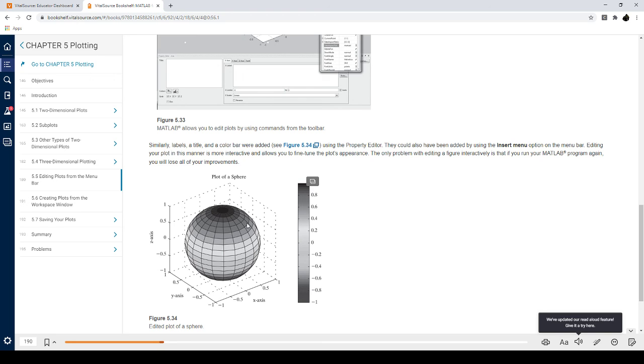And this is something that you'll see a lot of in FEA. Whenever you start doing simulations of designs, there's usually a color scale attached to it that tells you where the sharpest stresses are, where the most stress is being located, and it helps you locate it faster using the color wheel. So for example, in most programs, if it's green, it's fine. If it's red, that's where it starts to become a problem. And they use the same thing in factor of safeties.